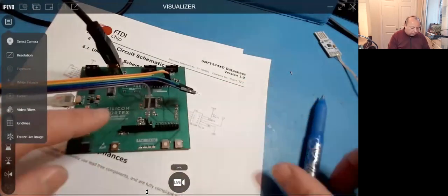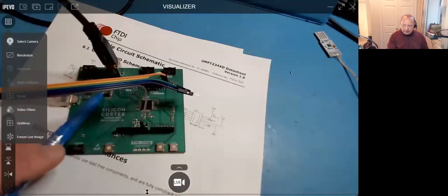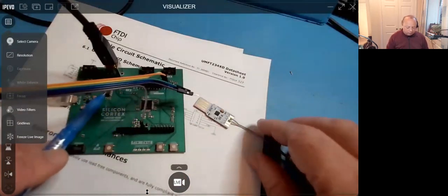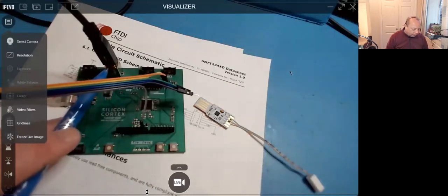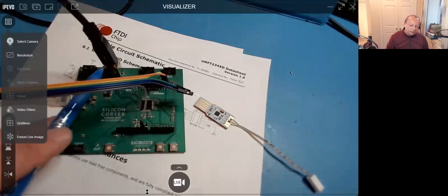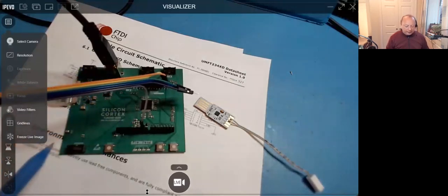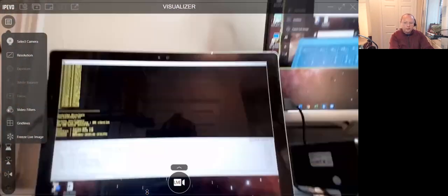Right, so this is my microcontroller in the middle. And then this is the UART chip in a different package to what we've got here, but it's pretty much the same. And then I've just got it going straight to USB. So it's a UART to USB interface chip, just a chip, there's no magic. And then that goes straight into the USB port of your laptop or your computer, of course. And then here's the first Wizzo.